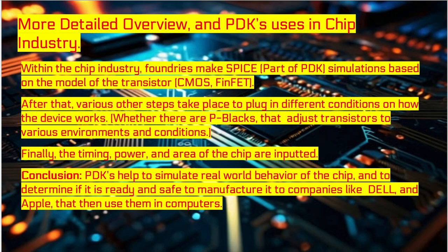They make these SPICE simulations, and in order to do that, they have to give the model of the transistor, whether it's CMOS or FinFET. Once they do that, they can make the SPICE simulations. The reason they do the SPICE simulations is because it's part of the PDK process. Once they do the whole PDK process, they can get results and analyze what the design of the chip is actually like, whether it's successful, unsuccessful, all of that.